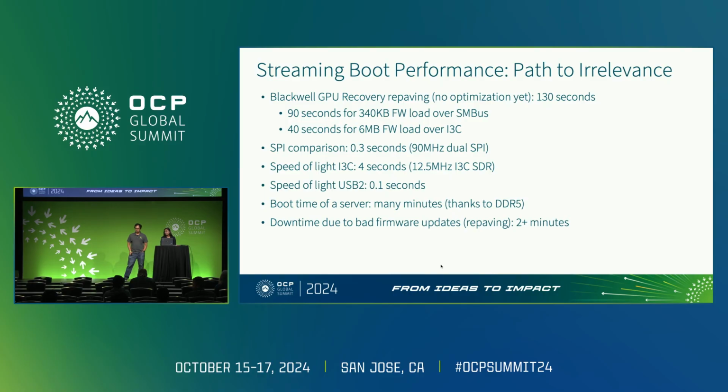Yeah, that's a great question. Storing per-device unique data, for example, like field replaceable unit data or manufacturing diagnostic data, so on, that hasn't been a goal for us because our primary objective has been to get flash out of the executable path. And I think to solve the data collection path, where you need data for field recovery, diagnostics, RMA, et cetera, that's going to end up being a problem that may be specific to the different kind of product that you have.